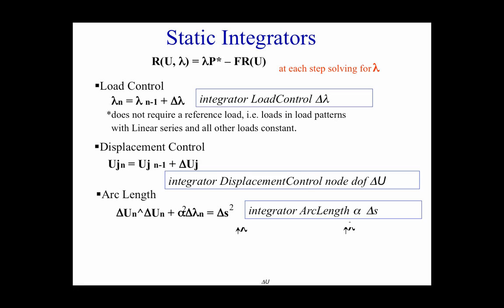So here's displacement control, which we saw this morning. If this is our load and displacement characteristics for the model, load control will get us up to here. But we cannot reach this point here, because the load response doesn't get up that high. So this is what load control does. With displacement control, we've got constant increments in the delta U. We're just marching along, figuring out what the load factor is to give us these delta U's.